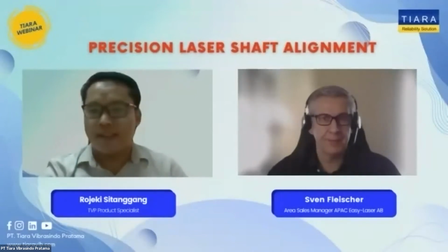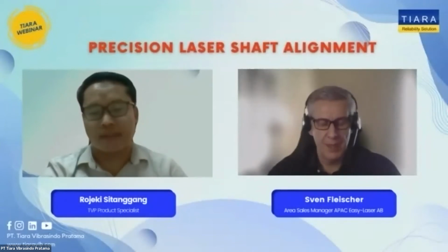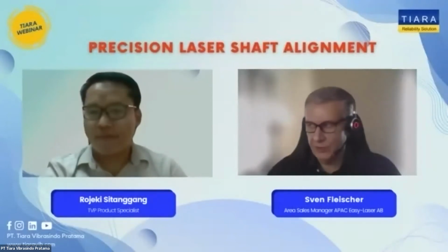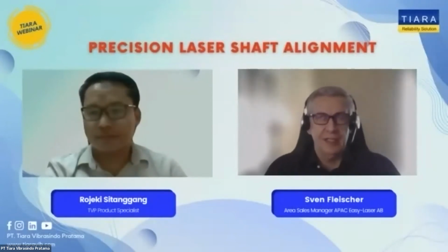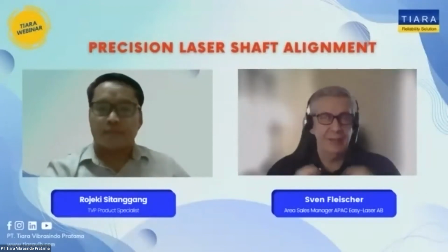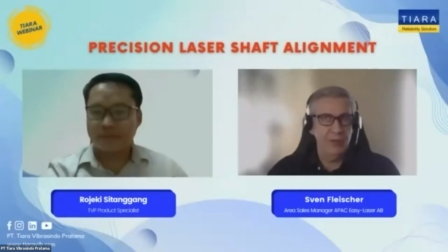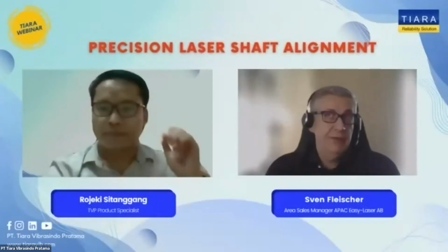Can the XT be used to measure in a plant with high humidity and high temperature, like around 40 degrees Celsius? Yes, absolutely. In general, the measurement units have an IP rating of IP68, and the default display has an IP rating of IP67. So it is very reliable in terms of protection inside very humid or hot places.